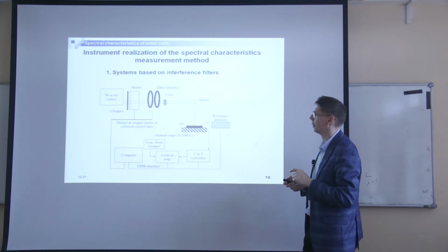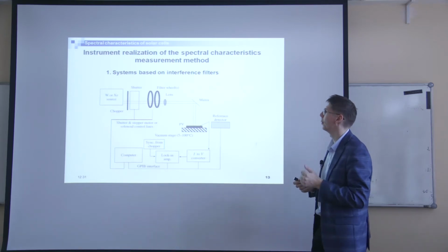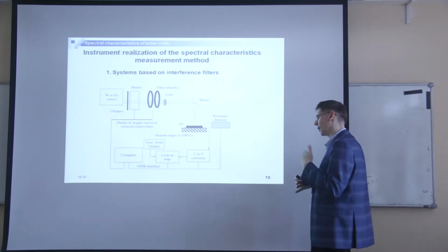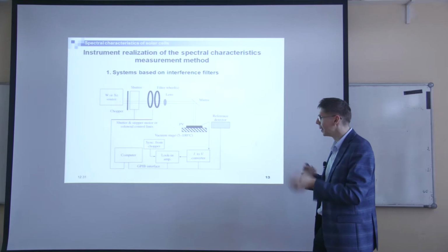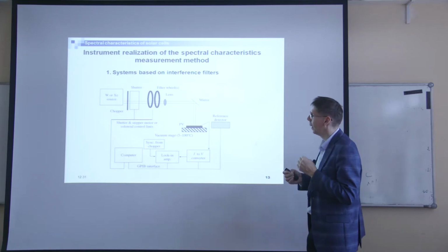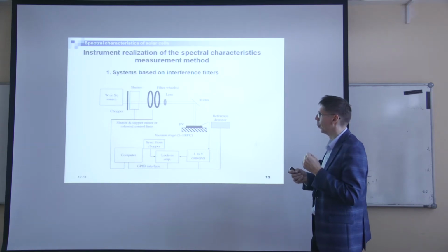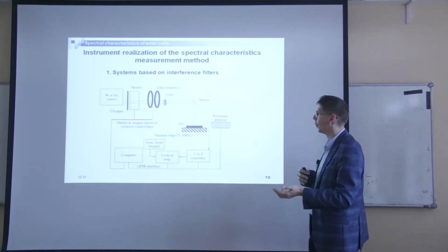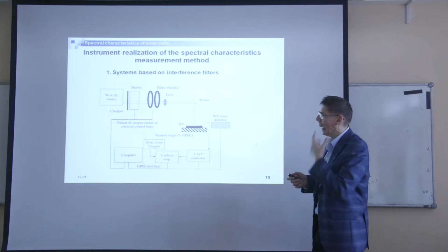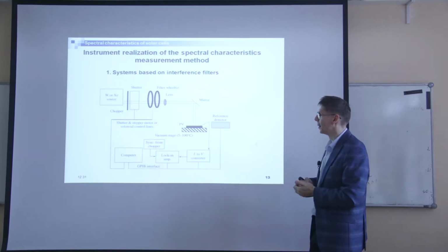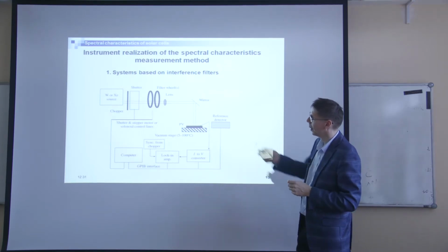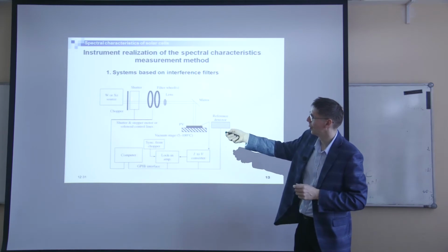But there is another important thing which is quite useful, especially for this measurement using the bias light: to improve the signal to noise ratio and to be less sensitive to the light, you have to use the optomechanical modulator, which is called the chopper.